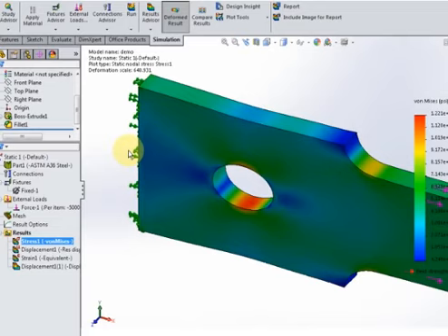This is mostly, I wanted to at least introduce the idea that you can calculate some stresses in SolidWorks. It'll show you insights that have to do with the stresses that might occur in members that might not have occurred to you unless you had this to show you, right? We might not have known about stress concentrations unless we had done some sort of an experiment with this, and it starts showing us, hey, it concentrated that stress a lot in these particular locations. Maybe we should do something about that. You know what I'm saying?